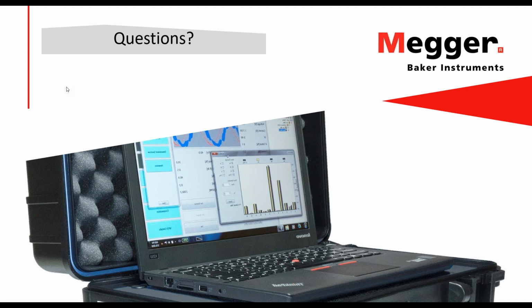Because what the instrument does is it senses the currents and voltages, and remember that it uses the induction motor as its own transducer, because anything that happens in the rotor of the induction motor is reflected back into the currents of the stator, because the load takes power from the motor via the rotor. Now that power is taken from the electromagnetic flux that's created in the air gap.